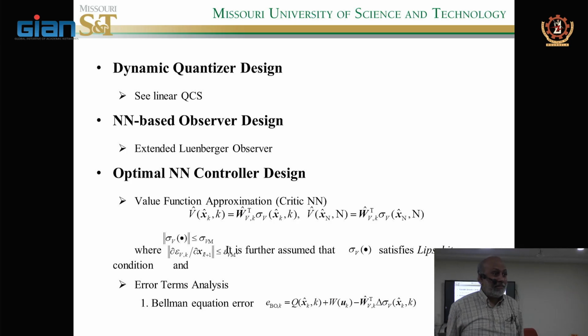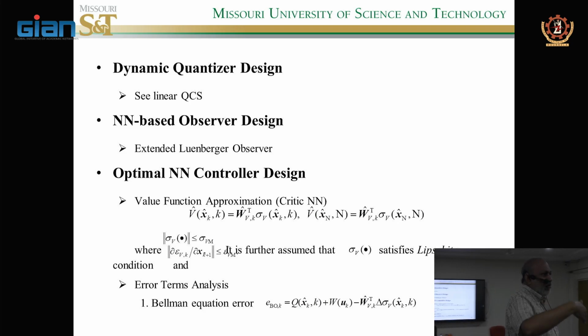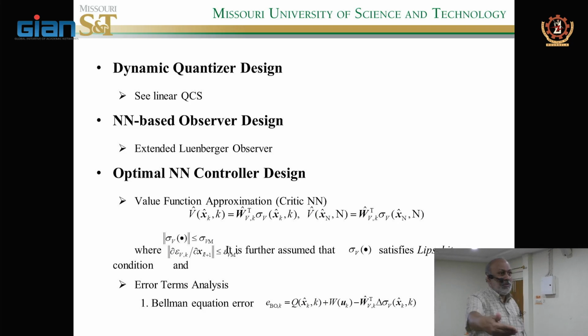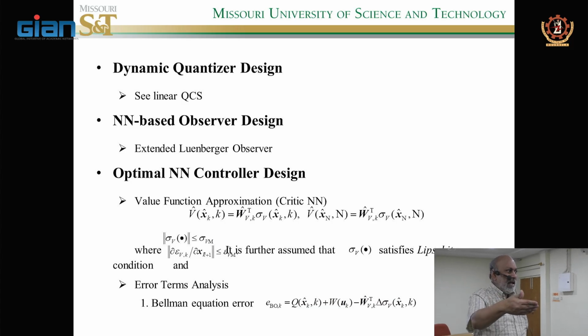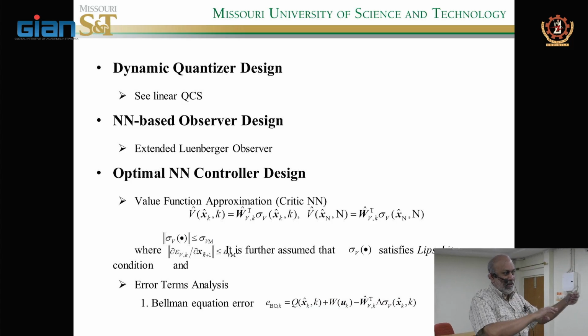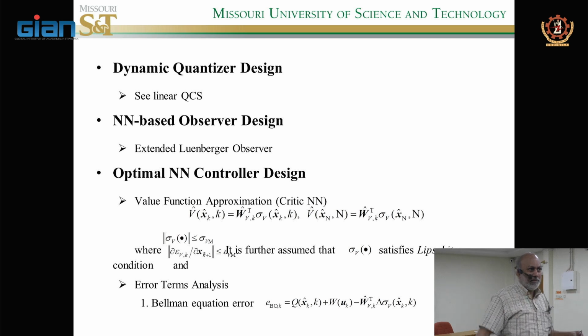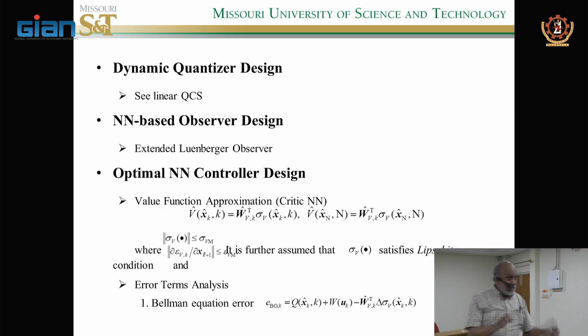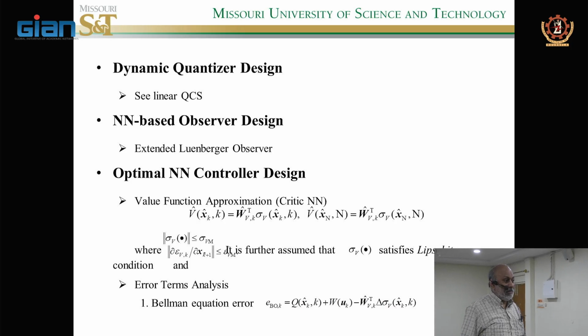So in feedback linearization, we map from one set of coordinates to the other. So that mapping has to be continuous, one-to-one. And then after you get the results in the other set of variables, you map it backwards. Unless it's a diffeomorphism, you really can't do a one-to-one mapping. So I want you to go back to your nonlinear control notes and check it. I'm going to ask that question tomorrow, right? I think it's important. I don't teach these concepts here, but they are needed. We normally don't deal with them.